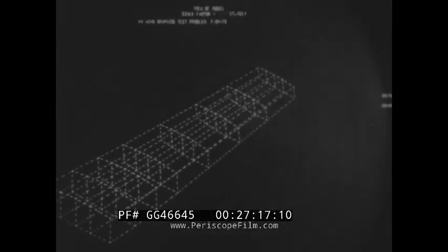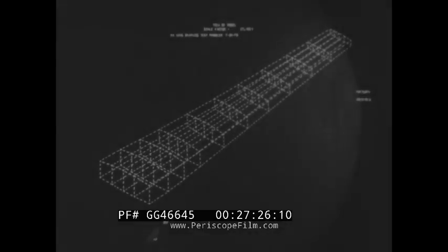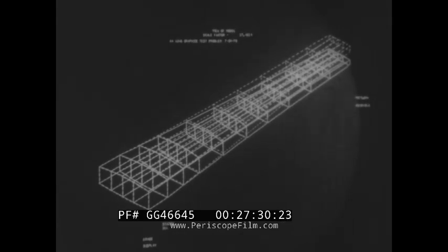After the model is analyzed, an overall view of the model in the deflected shape can be constructed. Picking bars in the coordinate transformation followed by plot produces the deflected view in dashed lines. The deflections of the wing are shown to scale. A comparison of the deflected and undeflected shape of the model can be shown by redisplaying the static view. Overlays of several loading conditions can be produced in this manner.